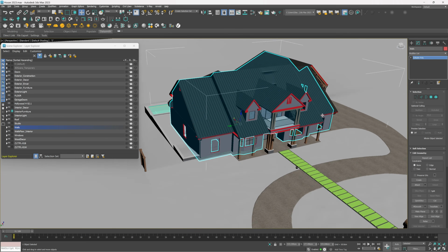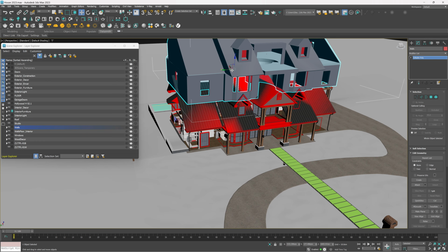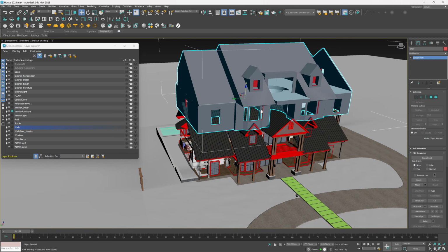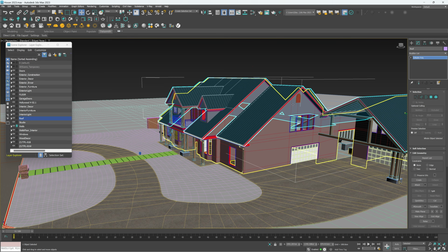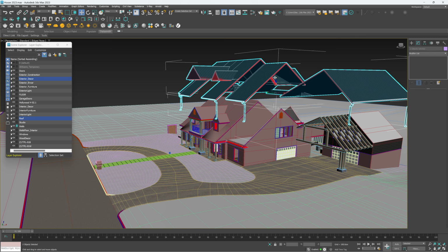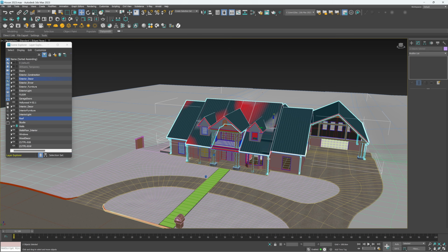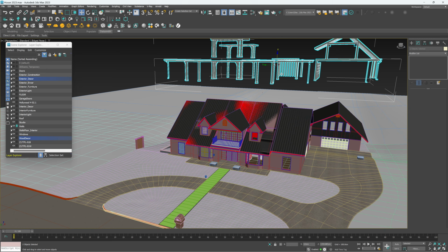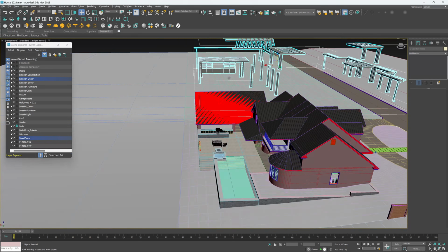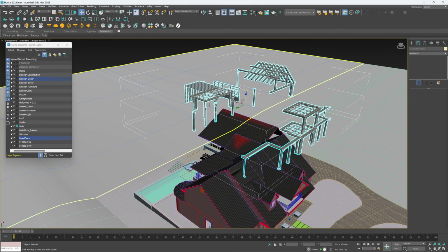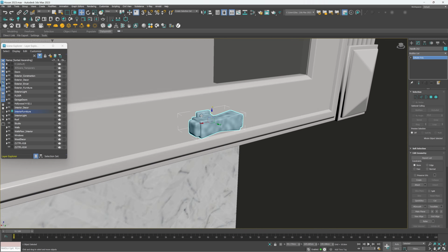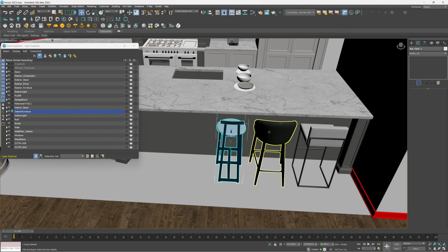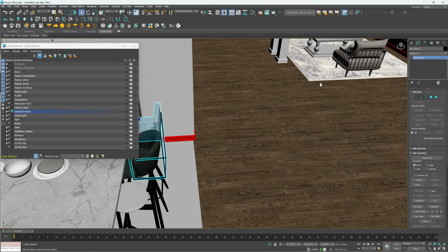I merged all the walls of the house and decor elements into a single mesh to reduce the number of draw calls. Later I will explain it with an example. I want to say that it was not the best decision and I will tell you why. All objects that have multiple copies I placed in a single copy, for example, windows, handles on kitchen drawers, furniture and fencing sections.